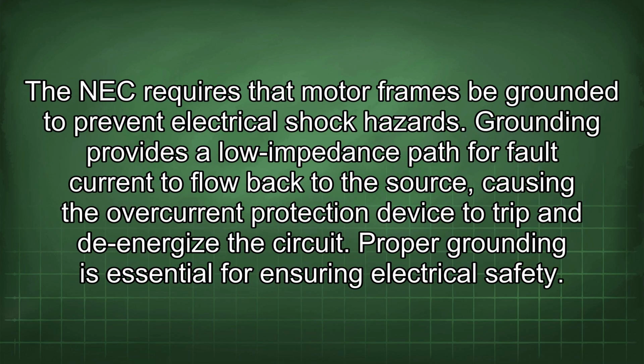The NEC requires that motor frames be grounded to prevent electrical shock hazards. Grounding provides a low impedance path for fault current to flow back to the source, causing the overcurrent protection device to trip and de-energize the circuit. Proper grounding is essential for ensuring electrical safety.